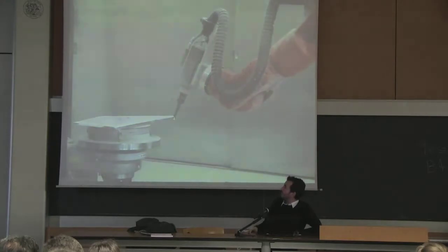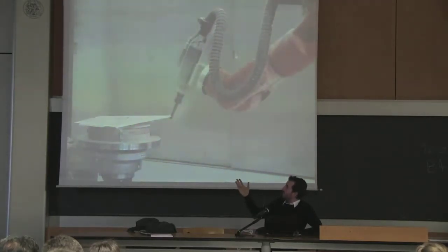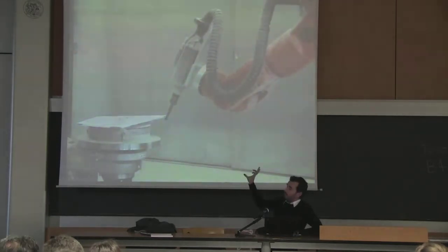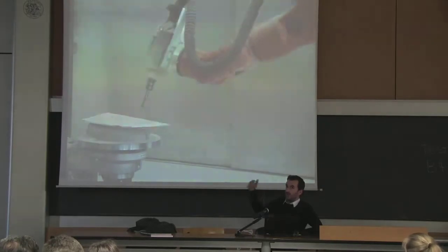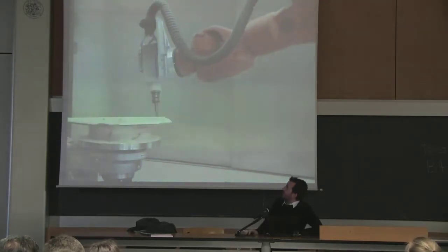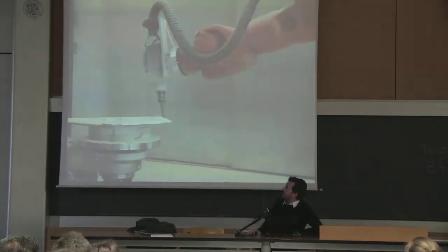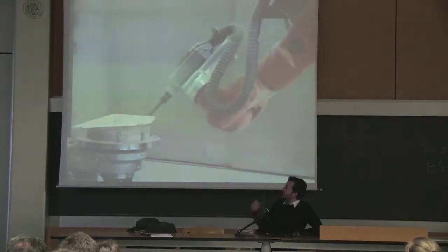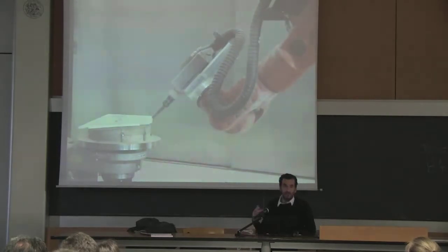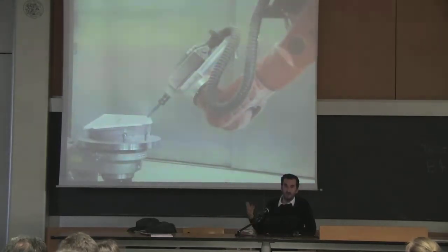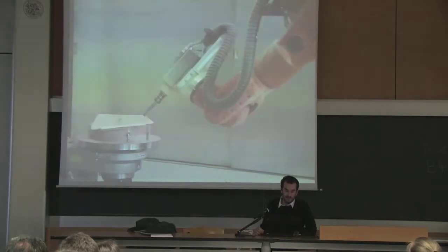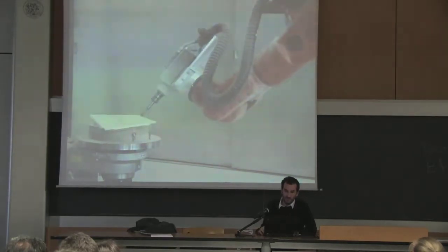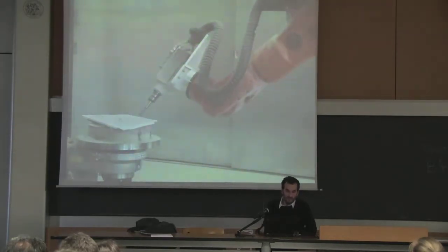So this is the way that these plates are made. Here already the plate is pre-trimmed by the robot on the turntable. So this is one robotic unit. The turntable is coordinated with the robot. And then the robot actually starts to cut these finger joints. And you can imagine that the tolerance of the joint is basically the tolerance of the tool, which is in the sub of a tenth of a millimeter range. One plate takes 3 or 4 minutes to build.